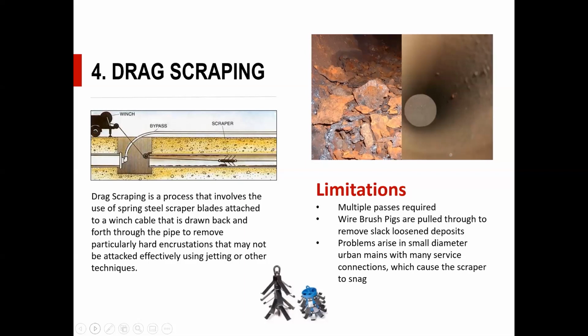One of the issues here is that it's quite a violent process when you're pulling these Christmas trees through the pipe, as we call them. So if you've got a lot of service connections, it's quite common for the scrapers to snag on the ferrules.